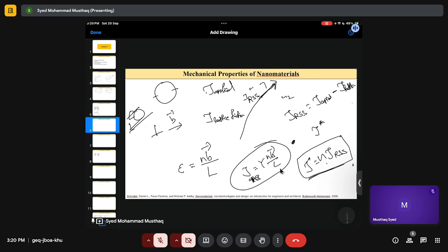If you cannot have a value greater than your friction value, then you cannot move, right? So if you can dominate the friction, then only if your applied force is greater than the frictional force can you move, right? So that's how we move on Earth also. The same thing goes for anything. The force should dominate the frictional stress, or should be more than the frictional stress. Same here. If your applied stress is more than the lattice friction, then only the dislocation can move.